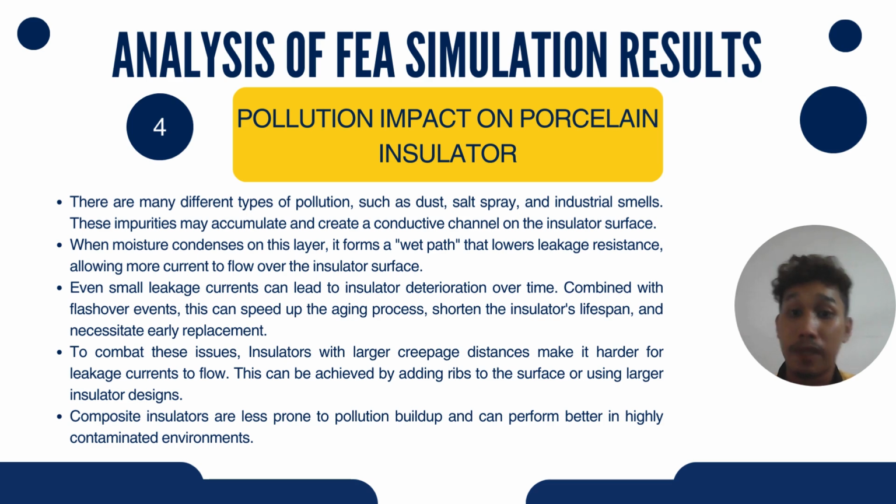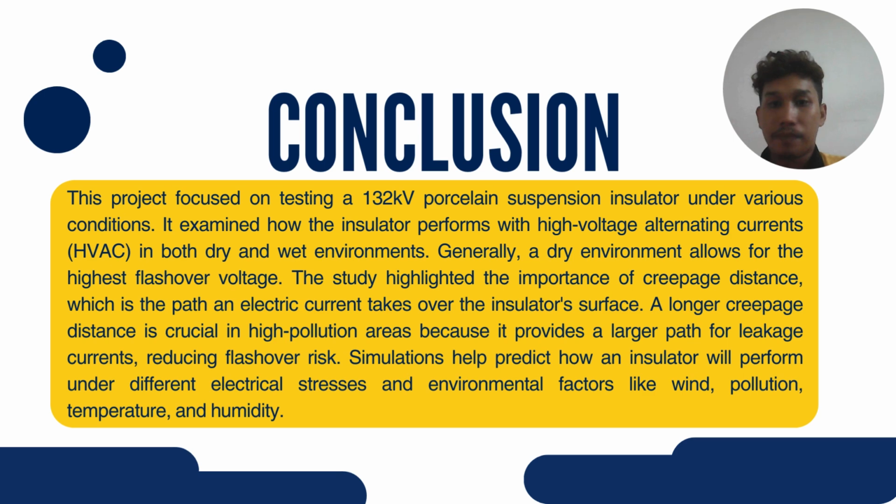necessitate early replacement. To combat this issue, insulators with a larger creepage distance make it harder for leakage currents to flow. This can be achieved by adding ribs to the surface or using a larger insulator design. Composite insulators are less prone to pollution build-up and can perform better in highly contaminated environments.